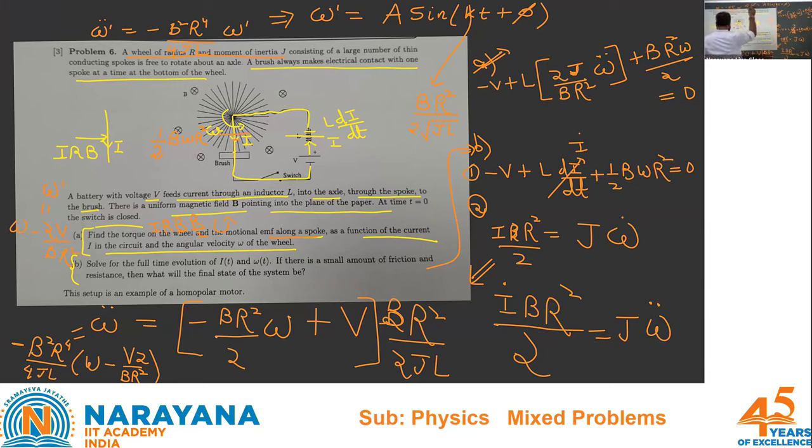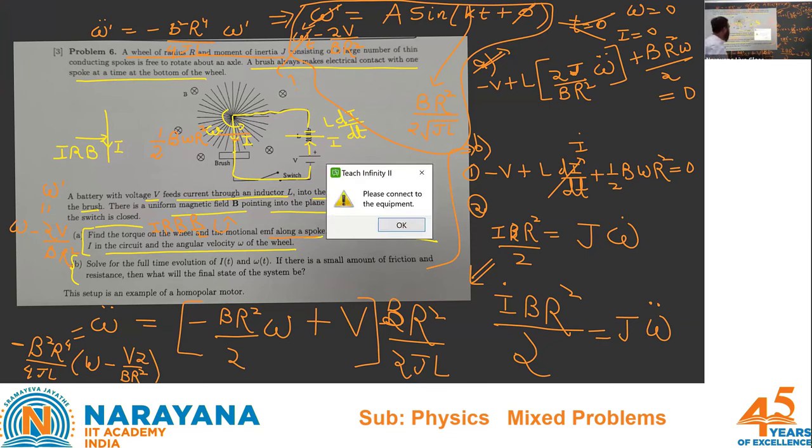And finally, you should substitute your omega prime as omega minus 2v upon br square. Now, I think the only unknown in this equation which is required, omega t, is your answer. There are two unknowns, a term and phi term, and you know two values. At t is equal to 0, now use boundary conditions. At t is equal to 0, you should make omega 0, and you should also use the current to be equal to 0 because inductor is there, so current cannot change suddenly. At t is equal to 0, angular velocity and current both are equal to 0.